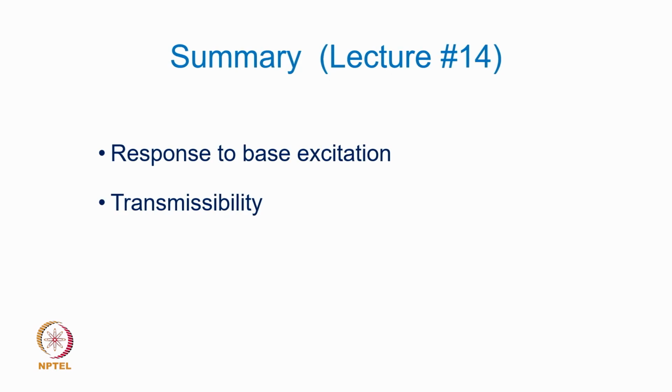So, this is the summary of this lecture. We had a small example of a vehicle traversing a wavy road profile, and in that context we explored the role of damping, the role of excitation frequency, and how by an appropriate choice of the suspension parameters, the response amplitude of the chassis can be reduced significantly. In that context, we discussed the displacement transmissibility. In fact, the response of the chassis to the base excitation amplitude is what we call the displacement transmissibility.